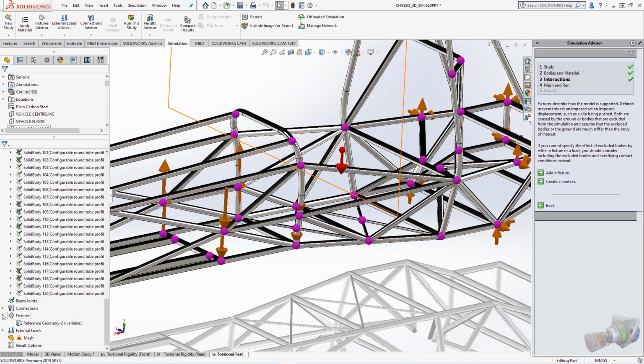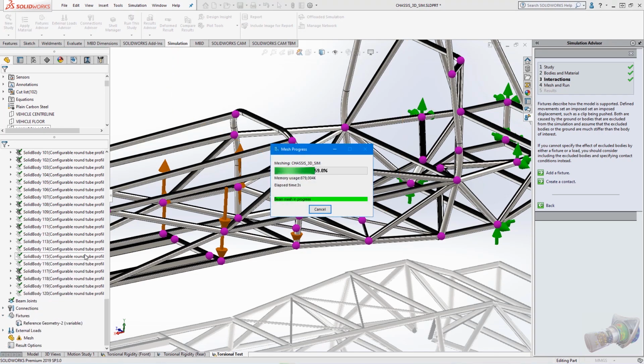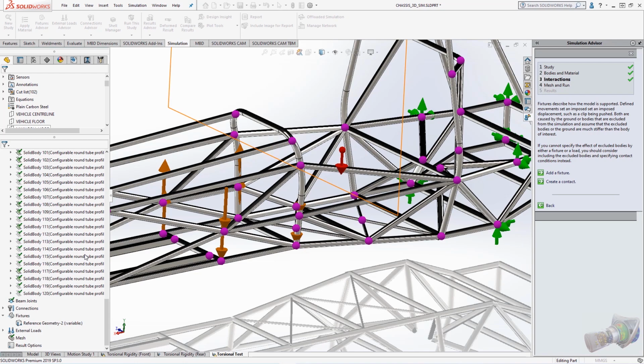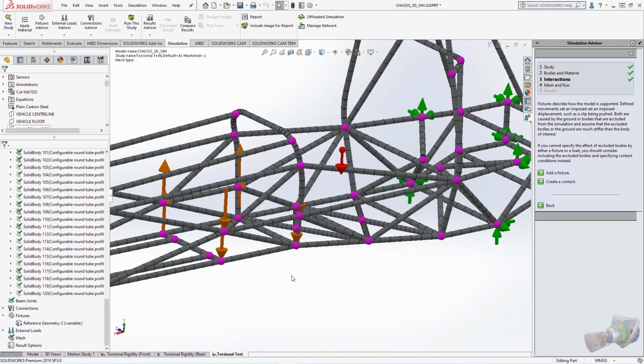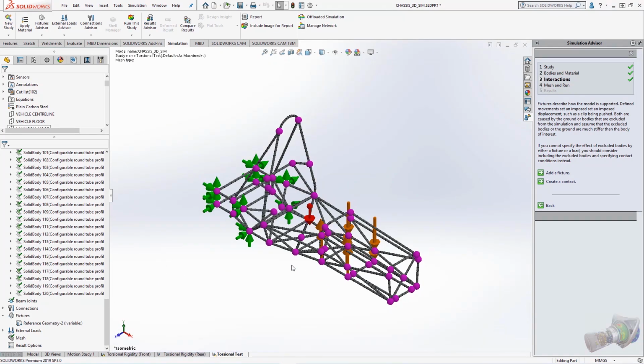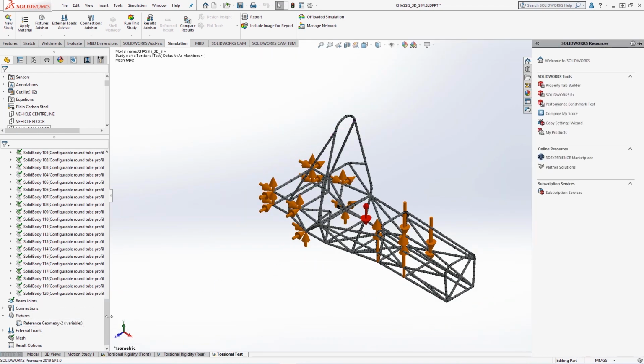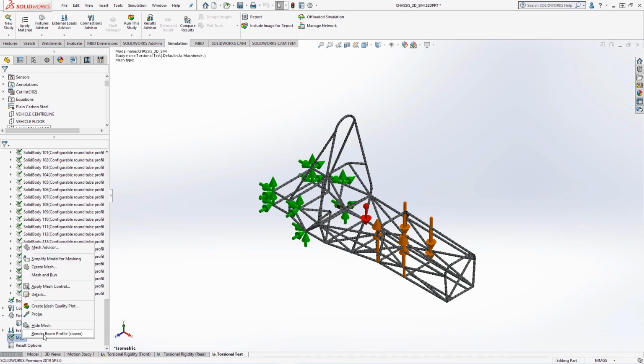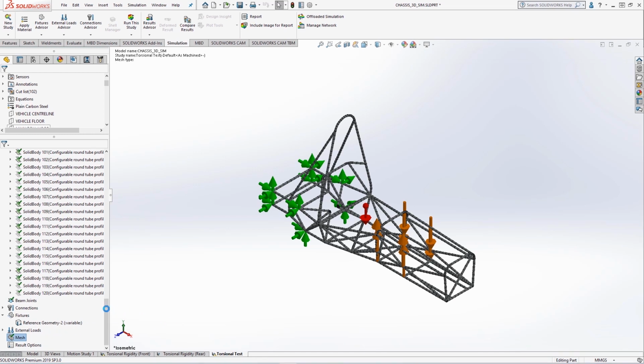Beam structures are incredibly lightweight and quick to solve, so meshing using this technique, a number of connected beam elements can be created in just a few seconds, which represent the frame geometry using tubular members. If the weldment beams are of different cross-sectional shape, you can right-click and render beam profiles in 3D. However, this is purely visual and does not affect the calculation.